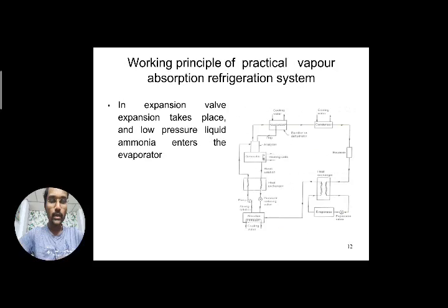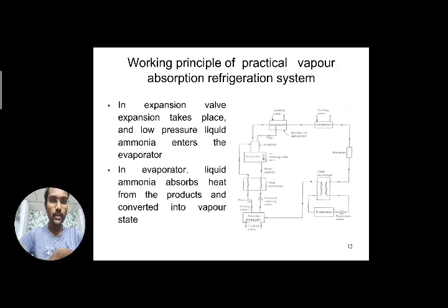Due to expansion, low pressure liquid ammonia enters the evaporator component. So it means, due to creation of very low pressures, low temperatures are created here. Now after the expansion valve, the liquid ammonia enters into the evaporator.